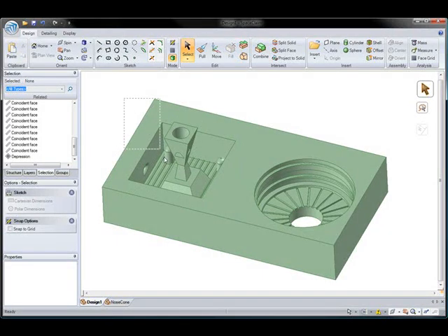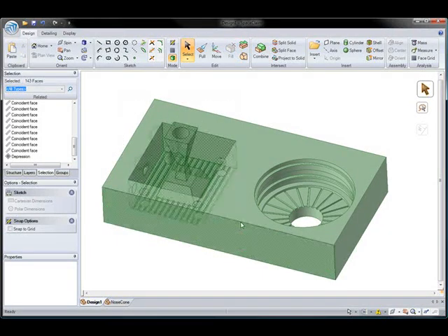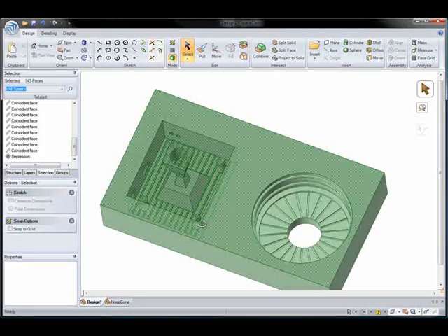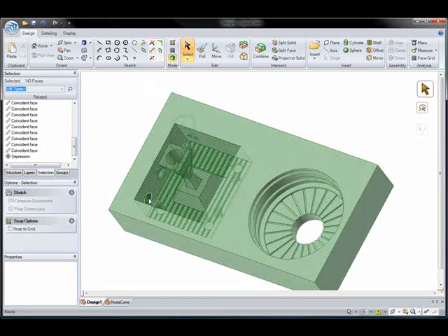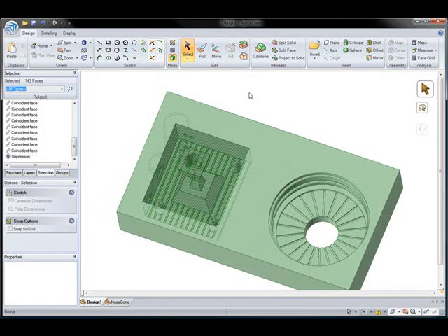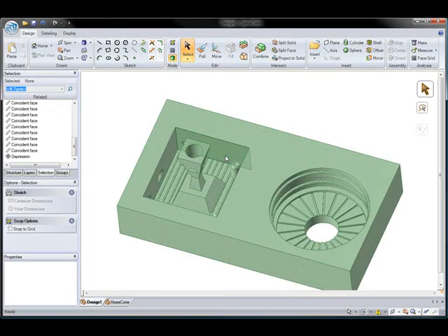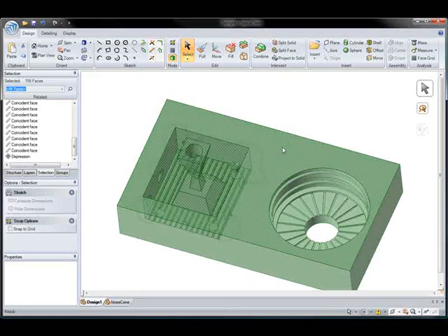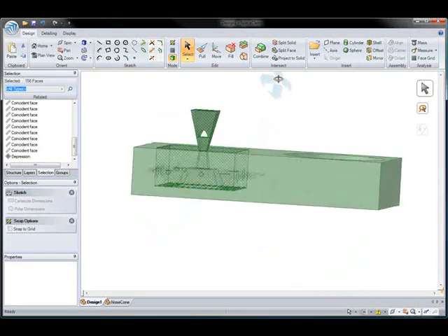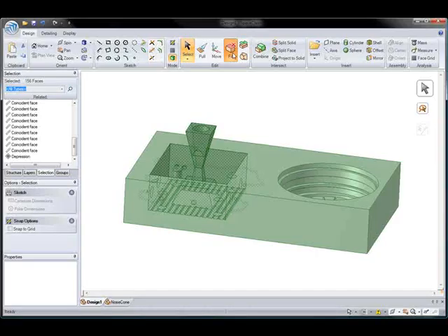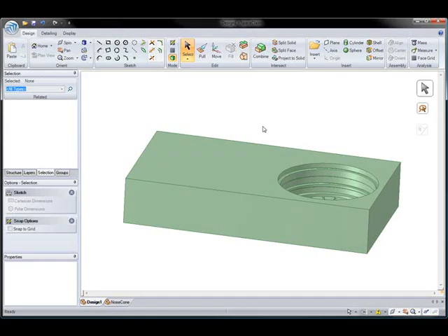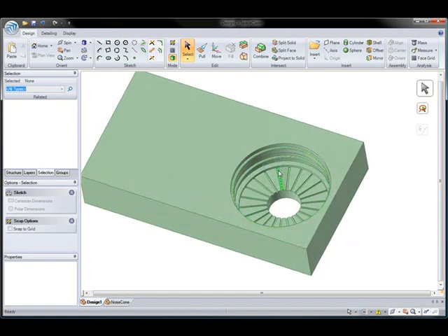And even if we sometimes try to box select the geometry, in this example, we can see that there's more geometry there. There's tubes running alongside of it that we couldn't really get in a box select. So using a bounding box, we'll just isolate all the geometry inside that's up to the surface we selected on. And if I press fill, we can get rid of it all at once.